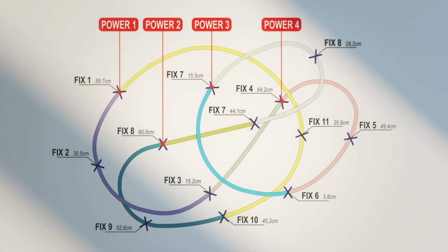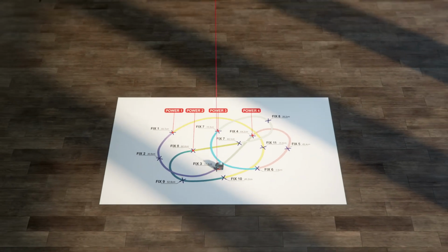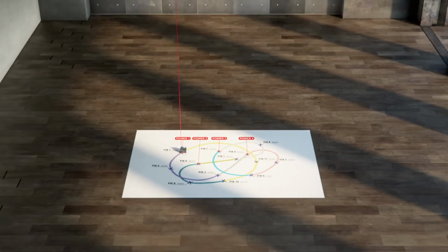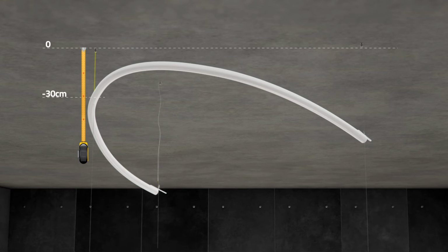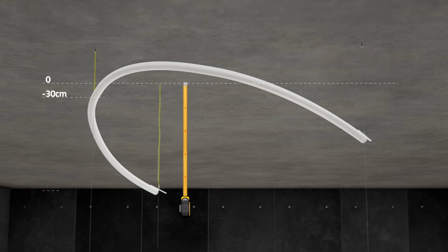3D structures mounting. Transfer the mark indications of suspension points from the template onto the ceiling using the laser level tool. Drill the holes in the indicated points and insert expansion plugs inside. Screw on the top part of the suspension. Lead out the steel strings and place them in the suspension's mounting element. Suspend the fixture using the measuring tape, marking out the string's length.